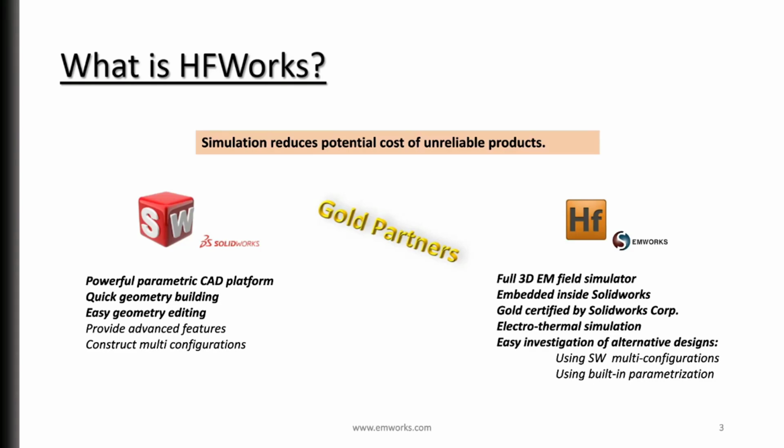It's fully embedded inside Solidworks. It uses Solidworks as a CAD. It's based on frequency domain finite element method, so it covers the whole band of the high frequency, going from few megahertz to some terahertz. It's also coupled with thermal analysis coming from the Joule effect.